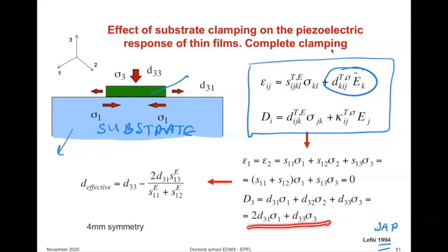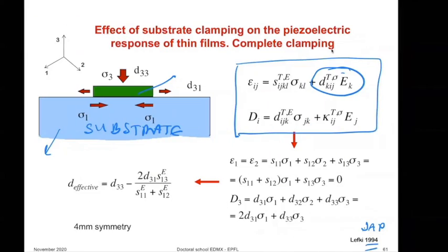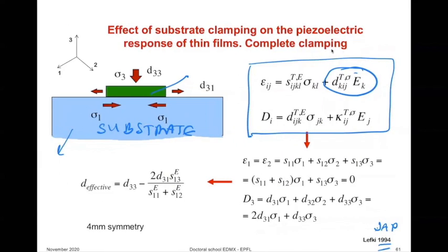So this will be the total charge. And from this relationship here, we can find what sigma 1 is, and we can replace it there and then calculate from the proportionality between pressure and the displacement the piezoelectric coefficient. So we can eliminate sigma 1 from this relationship here.